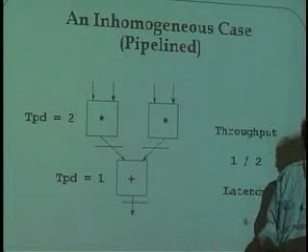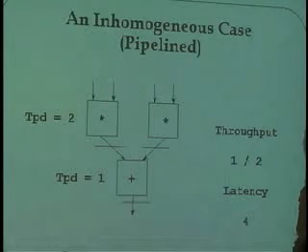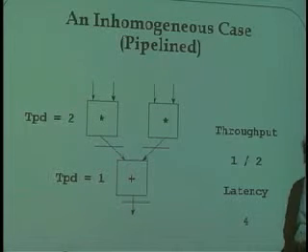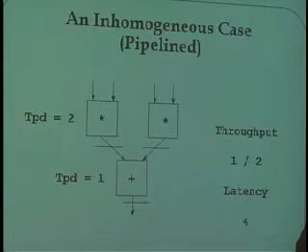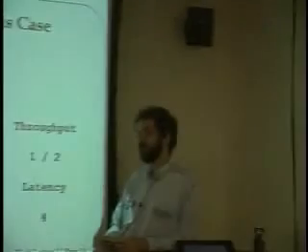Yeah? When would we be concerned with latency? Because it seems as though in most situations we'd be doing such a volume of calculations that throughput would be our overriding consideration. We wouldn't really bother so much about having bigger latency. So in general, that's true, but let me give you an example. Latency is very important in feedback systems and in some communication systems as well. So if you're having a telephone conversation and you're going through a type of speech processor that has a lot of work to do in order to compress your speech into very few bits, in general, you pipeline those things, and the throughput is very, very high.